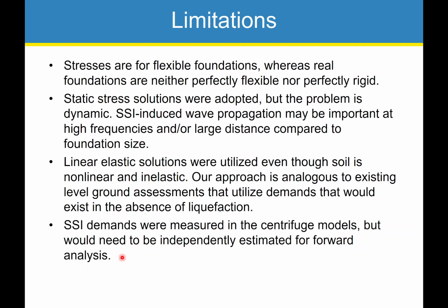In our case, we used SSI demands that were measured. We had accelerometers on the structure. We knew its mass. We could compute base moment, base shear. We knew the vertical loads. In a real problem, those would have to be estimated. And so this is where you would need to work with a structural engineer, right? Maybe you could take the results of a nonlinear structural analysis to get the base shear and moment to estimate ground failure. Now, that would require iteration and communication. Geotechs often do their work at different times than structural engineers in the context of a project. So this is a difficult thing too that I think can be overcome.